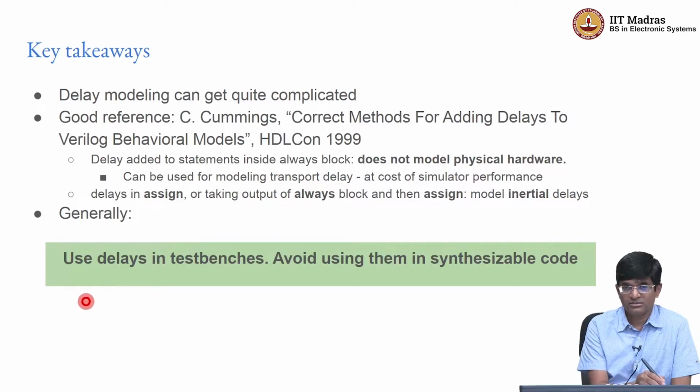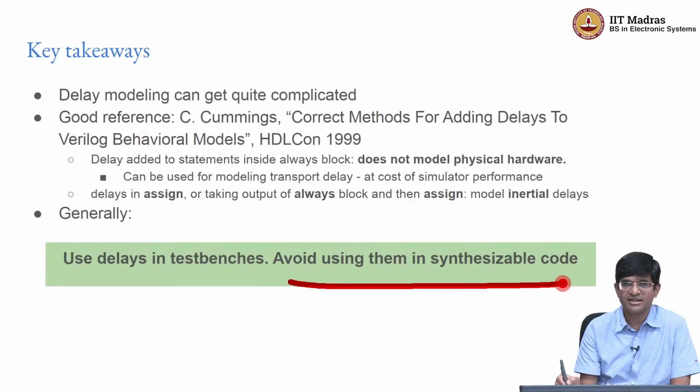And a rule of thumb that we can follow over here is that using delays in test benches is fine. In fact, we need to do it so that we can stagger out the application of stimuli and so on. But if you use delays in synthesizable code, stuff that you are actually using to model the hardware that you want, very likely you are going to run into some kind of trouble unless you are doing it in a very controlled and very simple manner, right. Any complicated use of delays in synthesizable code is most likely going to end up not behaving the way that you expect.